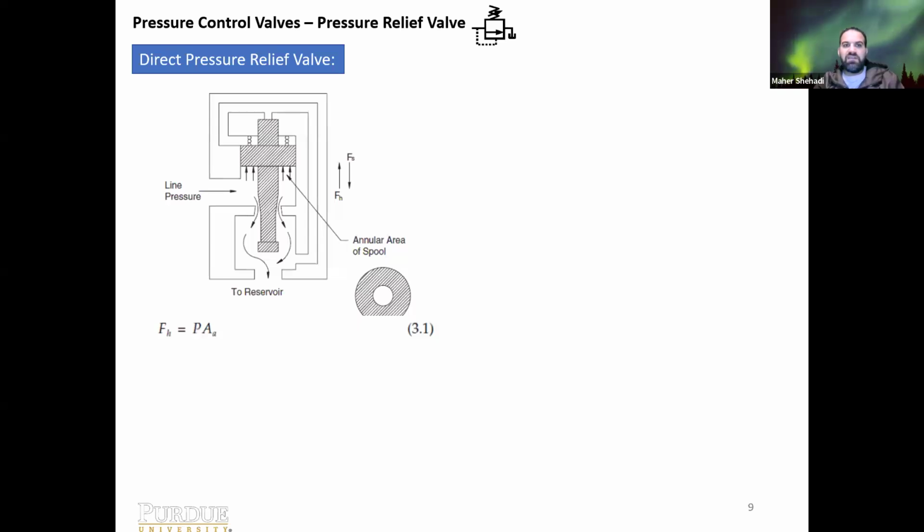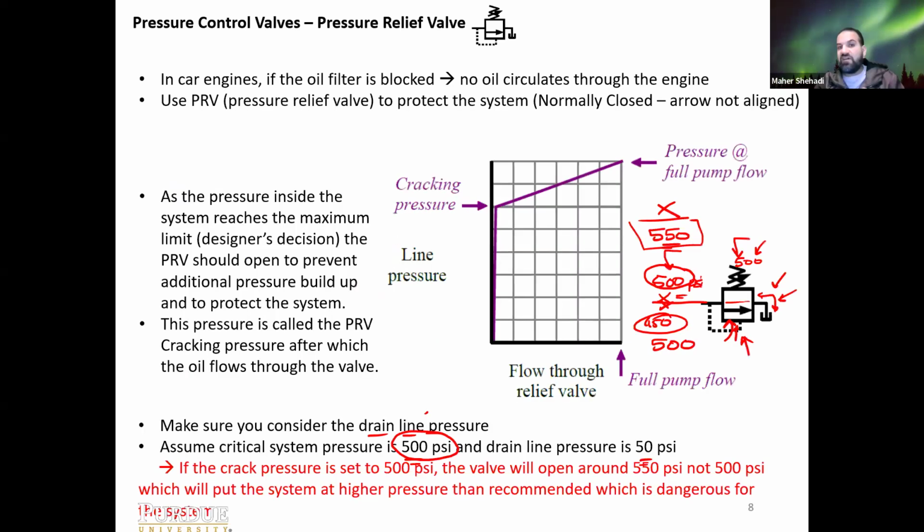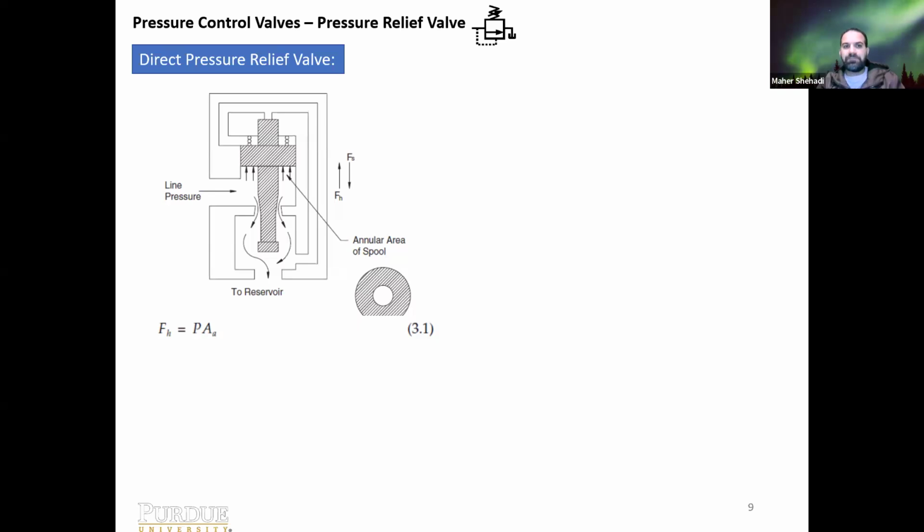Okay, this is called the direct pressure relief valve. We have some that are indirect, while this one senses the pressure directly in the upstream line. This is just a sectional view for that. So you have this poppet, as you can see, it's curved at those two lines here and here. In its normal position, it would be sitting on this base, so it's blocked.